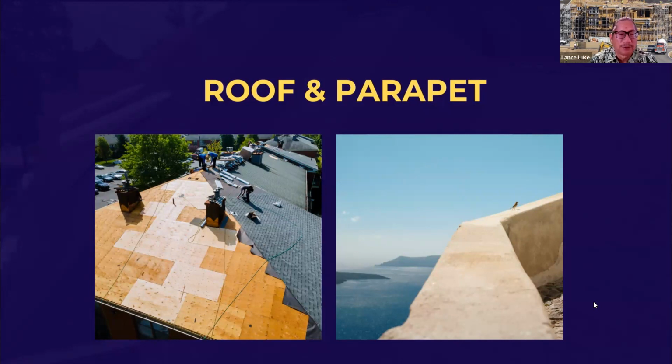Okay, so this is basically a hip gable type roof, and they're installing asphalt shingles. If you see on the bottom all that wood colored section, that's the plyboard decking. That goes over all your structural framing, and basically that's the roof structure. Then the contractor puts down roofing paper or some kind of waterproofing membrane, and then the asphalt shingles are installed.